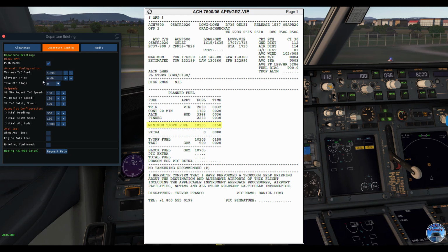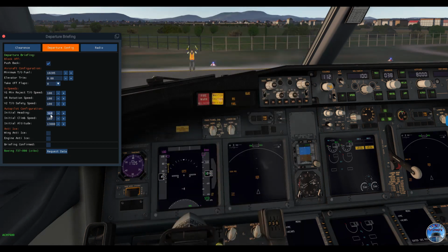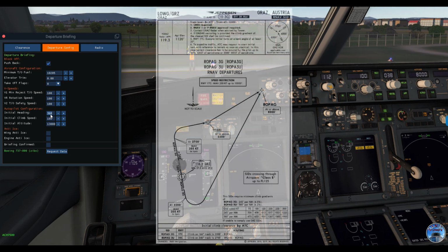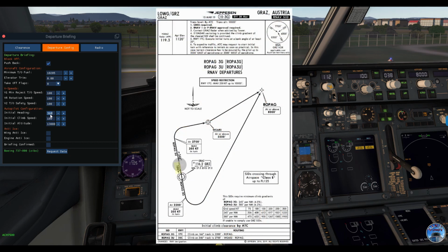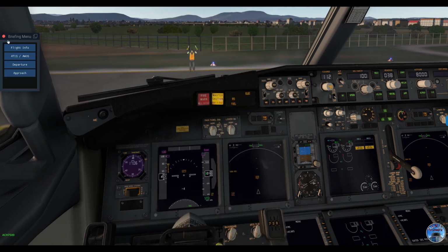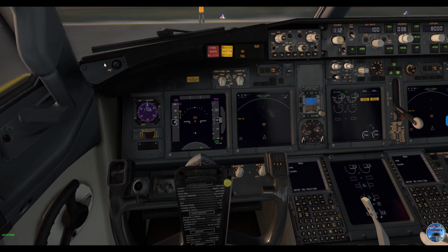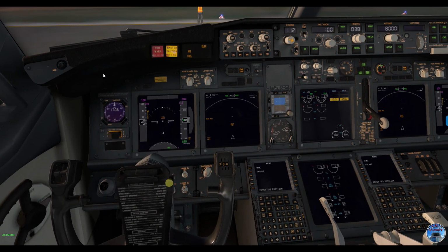Most of the other settings we get afterwards from the flight management computer. Just the initial heading we have to take over from the charts, and it's the runway track of 17 center. It's heading 166. All other data we get after configuration of the flight management computer. That we can do now. Go to FMC, position initialization.